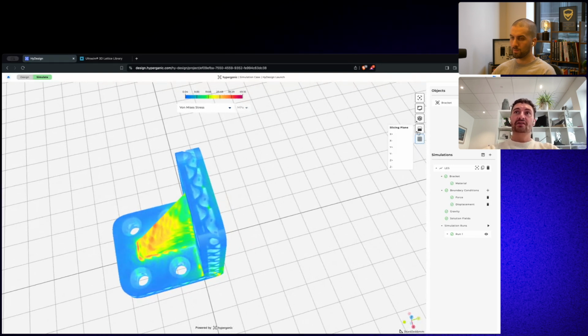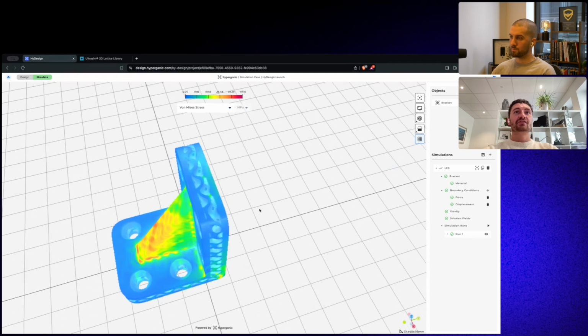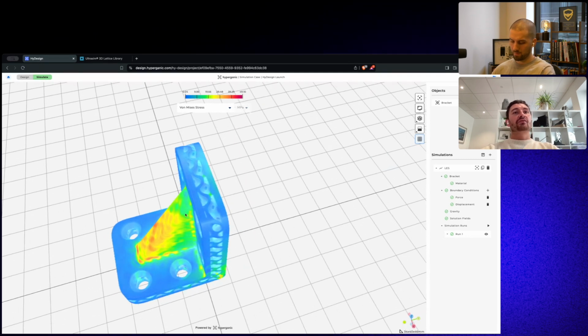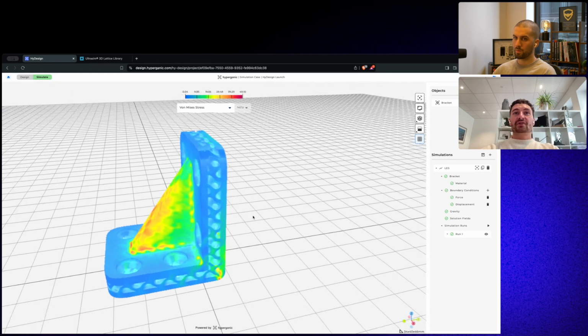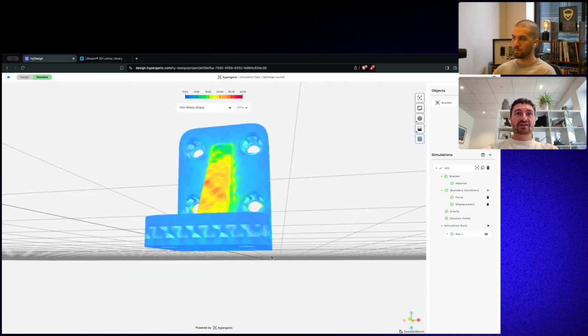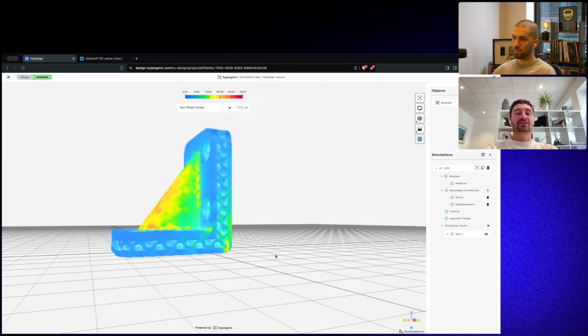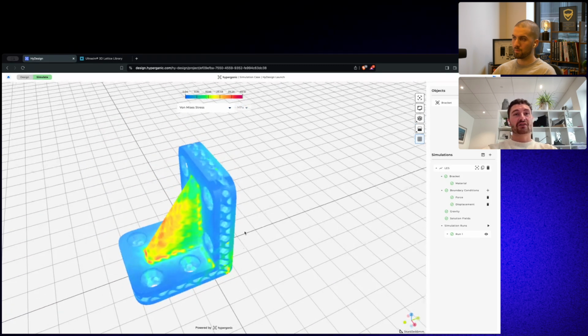So in traditional CAD or in traditional simulation CAE packages, you would run this object here through a meshing process, which means you take the part and you fit a finite element mesh that is body fitted to your object. So that means all the simulation elements effectively are inside the solid structure here, and all the empty volume would also be empty, ideally. As you can imagine, approximating a structure like this is going to take quite a lot of time. It is going to be quite compute heavy.